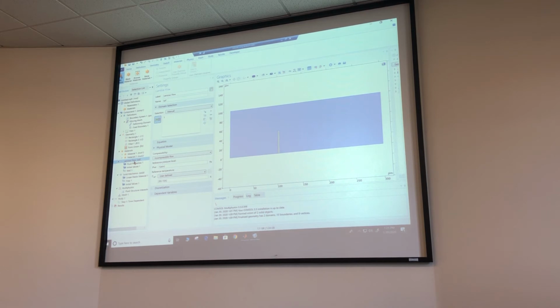Okay, so this is what you want, and you don't want that. That's for laminar flow. For solid mechanics, you want this, but not this. So that's for that one. Now when you go in material one, you only have 2 options, density and viscosity. So 1,000 here, 1 point E negative 3 there, and then 1 E negative 3.